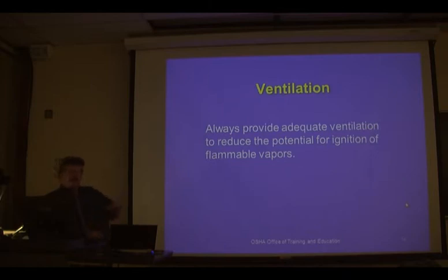If you're below this concentration of that material, there's not enough there for it to burn. If you're above that, it also won't burn or explode because there's probably not enough oxygen there or it's just too concentrated. So there's limits on when certain components will burn: lower explosive and upper explosive limits, lower flammable and upper flammable limits. Okay? So what ventilation does is you need to have adequate ventilation. Remember those words, adequate ventilation.